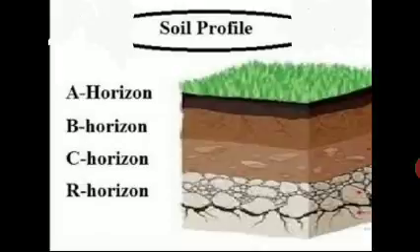Blocky: in blocky topsoil, water entry is moderate. Massive: in topsoil, massive structure blocks the entry of water. Seed germination is difficult and aeration is poor. From the standpoint of agriculture, permeability of soil to water, air and roots provided by favorable soil structure is important. Favorable soil structure is the key to soil fertility.